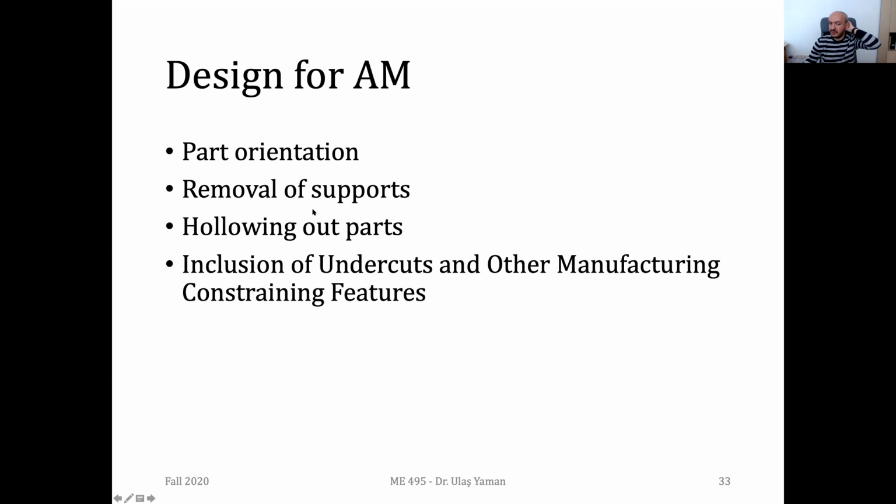especially if it's a photopolymer system, we don't need to use completely filled products. If you consider this bunny, I printed it by using an SLA system and photopolymer system, but I didn't hollow it out. The interior of this bunny is completely filled with material. It's not a good approach, since photopolymers are quite expensive. So it's better you do some hollowing out and try to decrease the amount of material we are spending for the fabrication of this part.